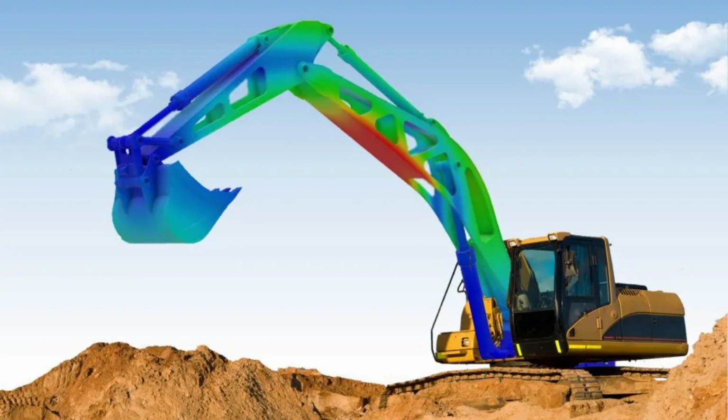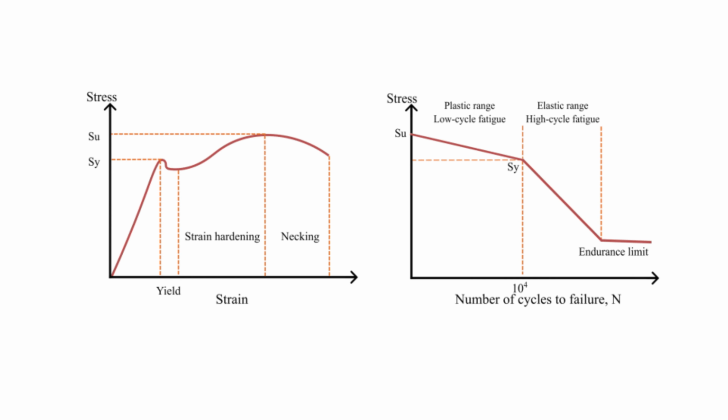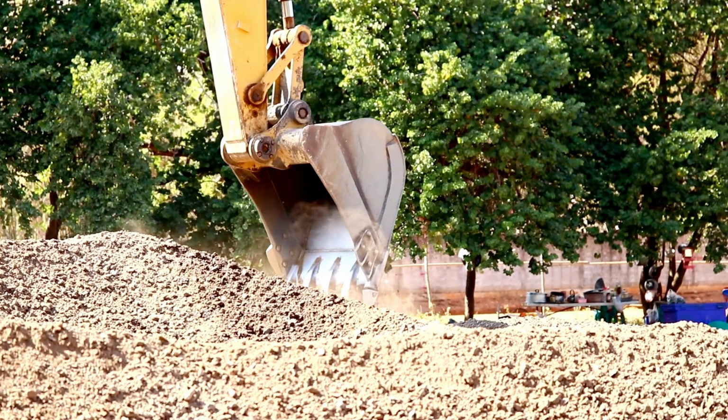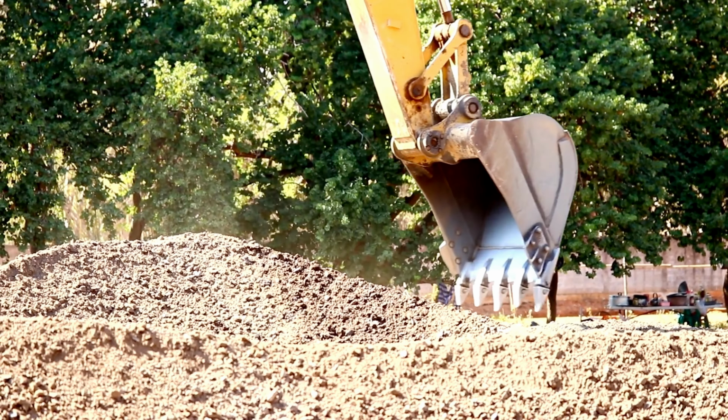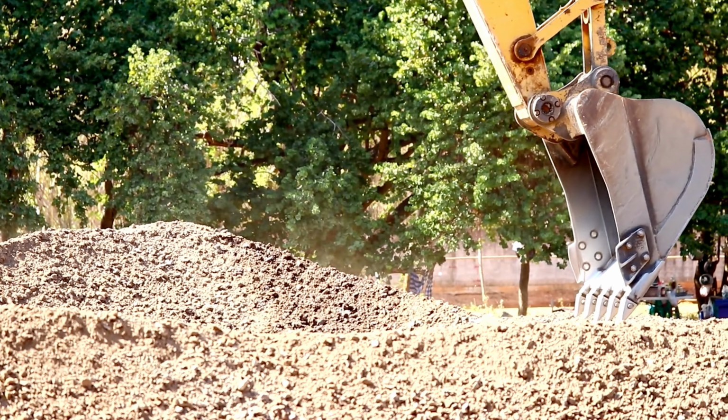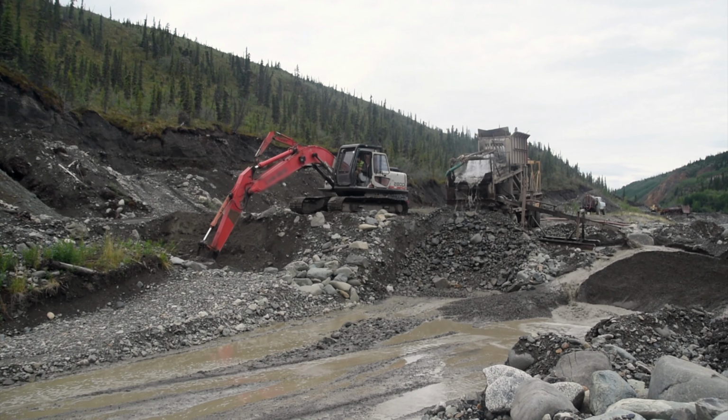In addition to static stress analysis, engineers conduct fatigue life predictions using methods such as SN curve analysis and cumulative damage models. These analyses estimate how many load cycles a structural component can withstand before fatigue cracks are likely to develop. Real operating conditions are also studied through duty cycle analysis, which evaluates the range and frequency of loads experienced during typical excavator operations. Based on these results, engineers optimize the structural design to improve durability.